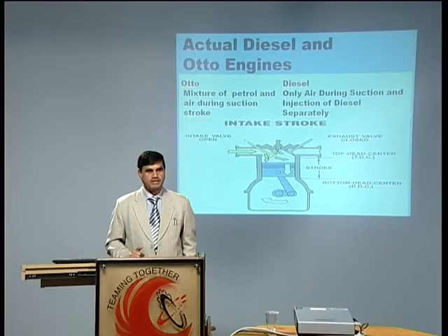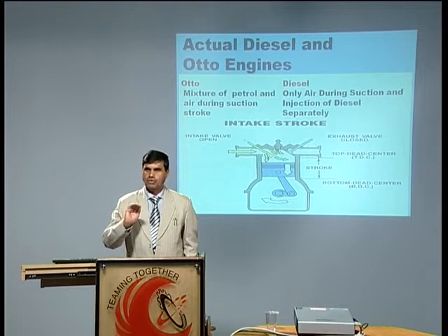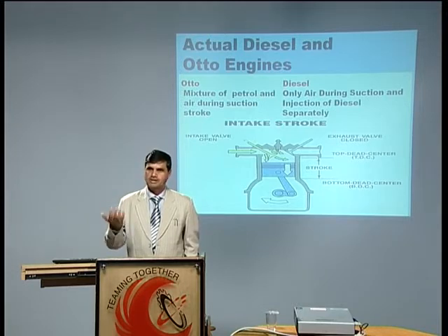The ignition temperature of diesel is significantly lower than petrol. The self ignition temperature of diesel is around 180 degrees, whereas that of petrol is 450 degrees Celsius. So even if no source of ignition is available, after compression the temperature of air is significantly higher. In that atmosphere, when we inject the diesel, combustion can start.